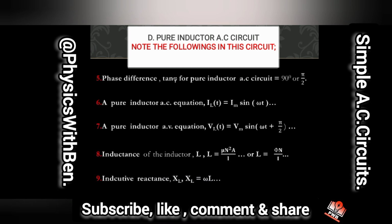Examiners may also ask you to state the phase difference for this type of circuit. The phase difference is this. Also, for the pure inductor, this is the alternating current equation, the voltage equation, and here is the equation for the inductance of the inductor: L is equal to mu n squared A over l, or L is equal to phi n over I.